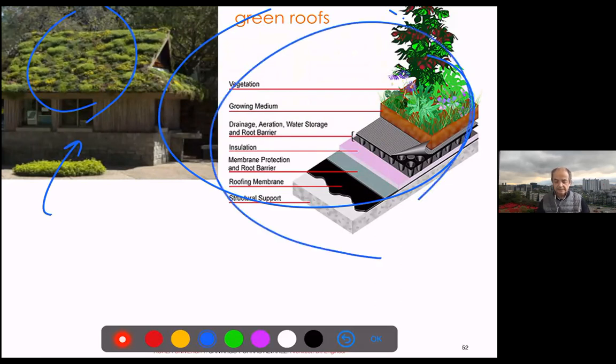But in general, the secret of the system is to have a filtering layer as we had in the basement walls with a drainage layer. Actually, this is the same material we use in vertical for this drainage, right? So in a very thin layer, you may have a clear separation between the sand and the insulation, and you don't have accumulation of water.